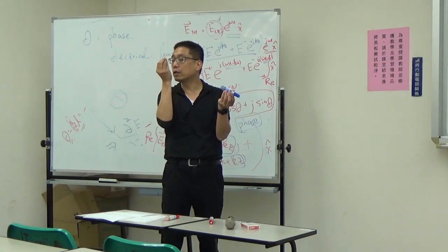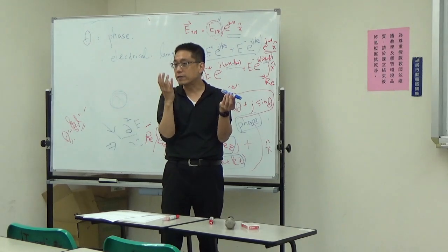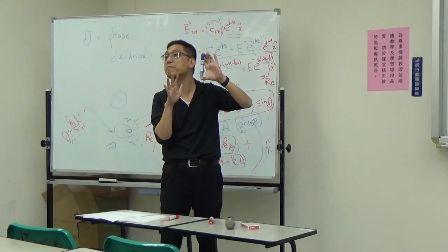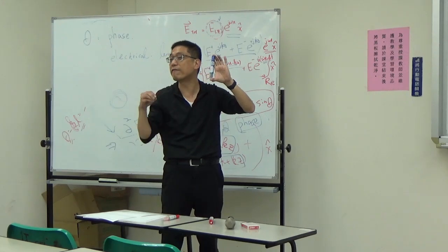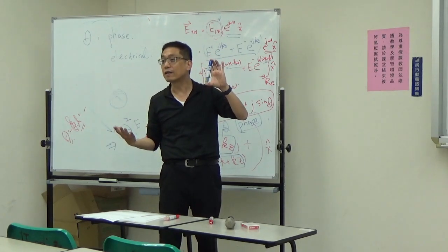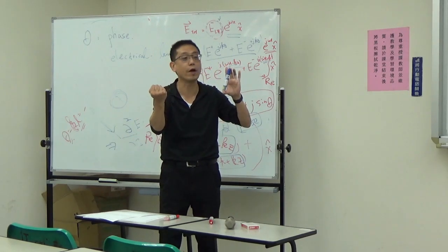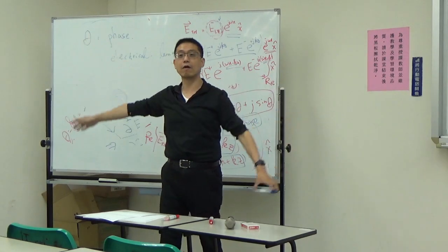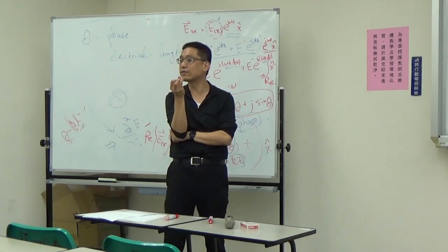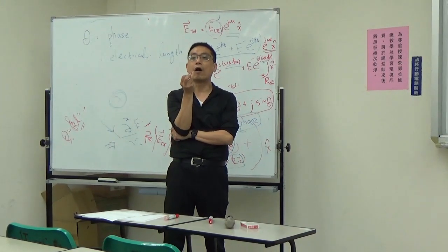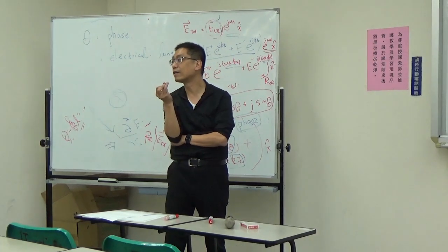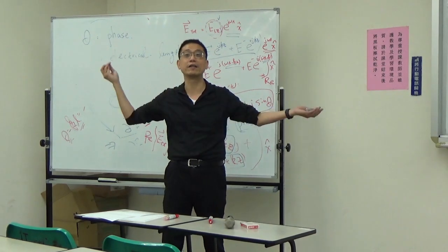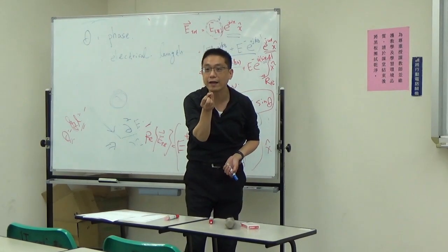So in different situations, at different frequencies of the signal, your physical length has a different meaning. If your frequency is very, very low, like DC, DC means f equals 0, right? There's no frequency. That means your wavelength is infinitely long. So any physical line is a point. There is no physical length at DC, because f equals 0, which means your wavelength lambda equals infinity. Everything is a point. You don't see any line in DC.